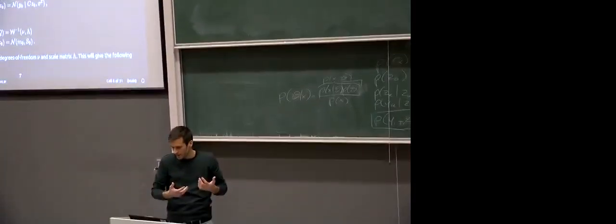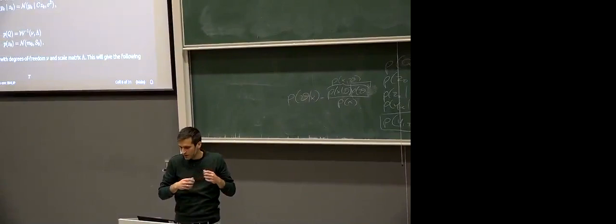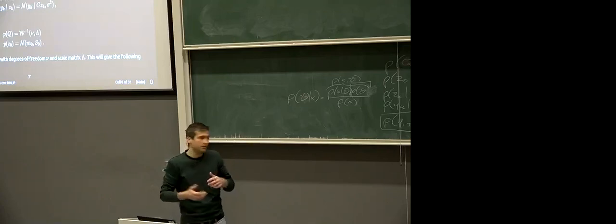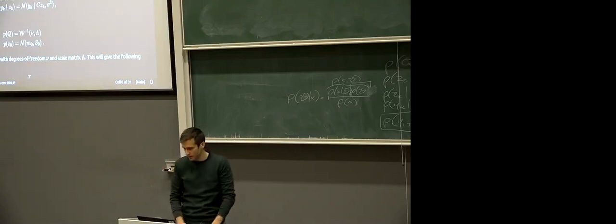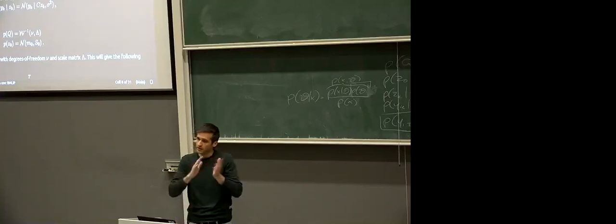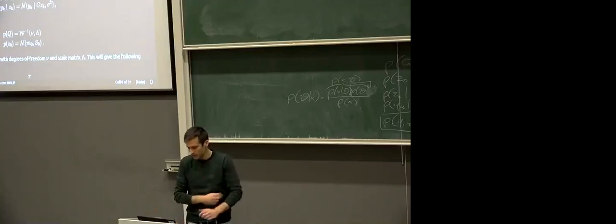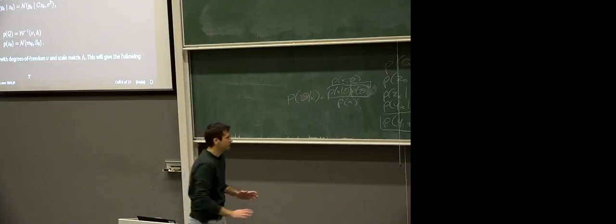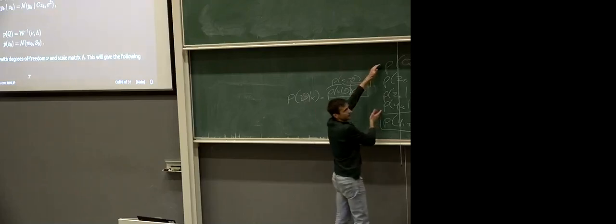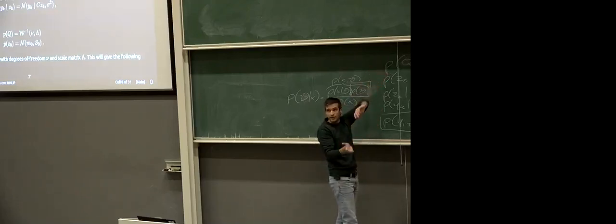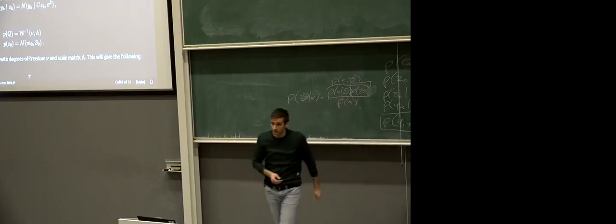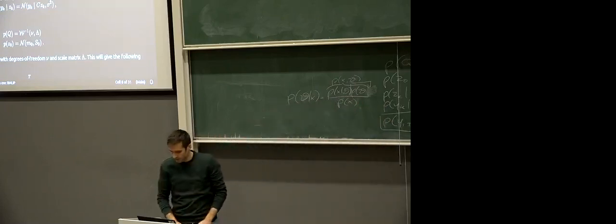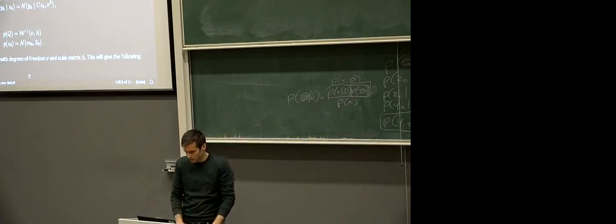But the main point of this toolbox is that if you're designing a probabilistic model for a particular problem, right here we're thinking of these shaking buildings, and we want to design a probabilistic model to do state estimation and process noise covariance matrix estimation, you only have to come up with a reasonable specification of what random variables depend on what else. What random variables depend on each other, what data depends on which random variables. That's your model structure, your model specification. That's the only thing you need. You feed that to the toolbox, and then it takes it from there.